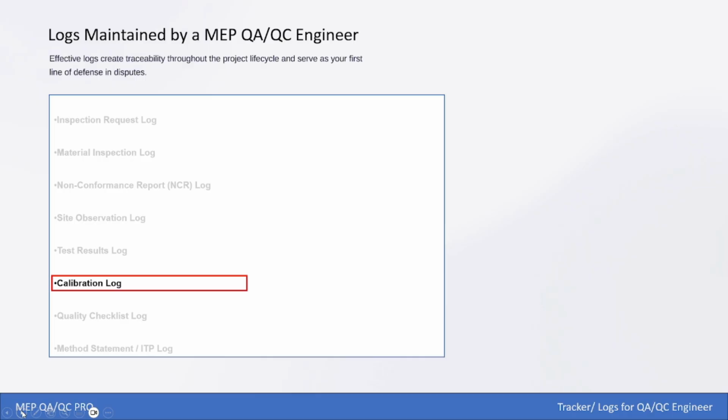There should not be any due or delay for the calibration. Whatever equipment you are using should be calibrated and the valid date should be there. So through the calibration log, you can track if something is going to expire in the next month or upcoming months, so that you can notify your team that this gauge or this megger machine is going to expire next month. So before that we need to renew the calibration, so that has to be tracked in the log.